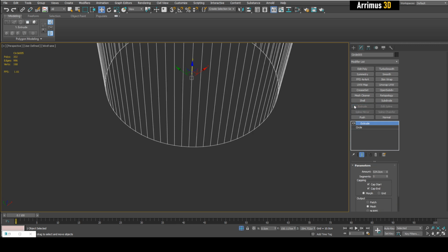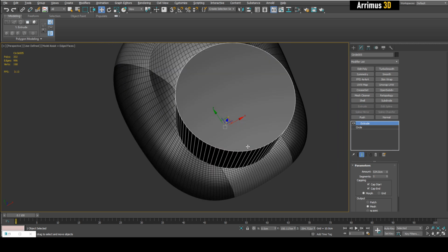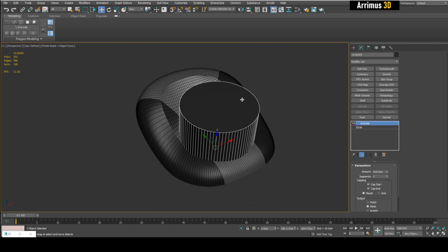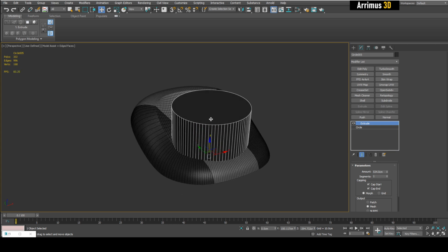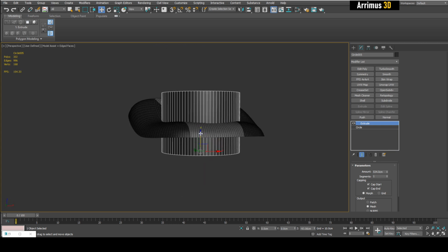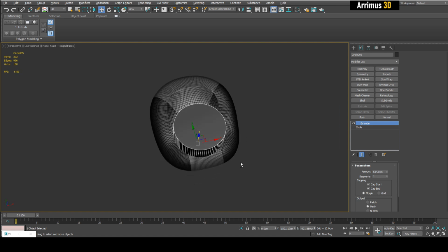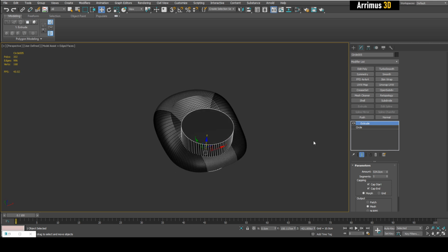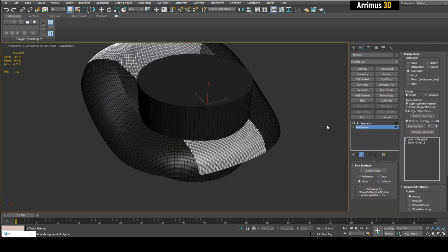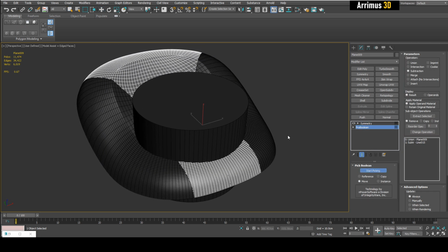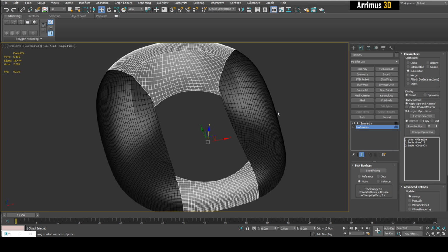And once again, we're going to extrude that. This time, since it's a closed spline, it's going to give us a volumetric shape here. Previously, we're just using a basic non-closed spline, which just gave us pretty much a wall. All right, I will select this and we will remove that.